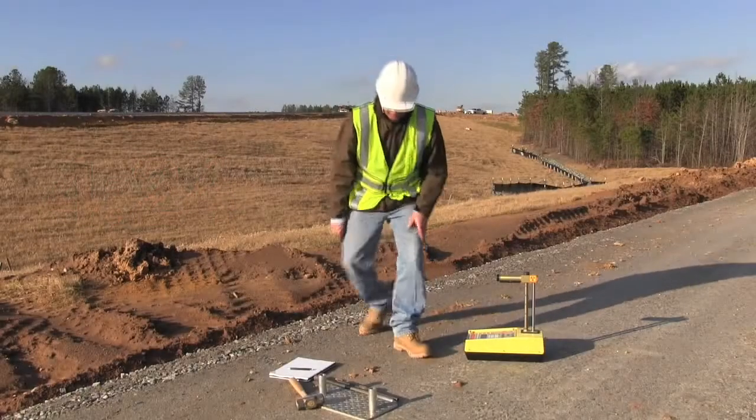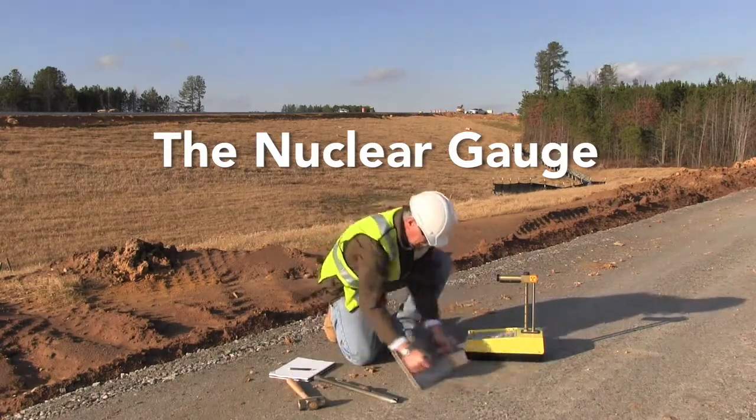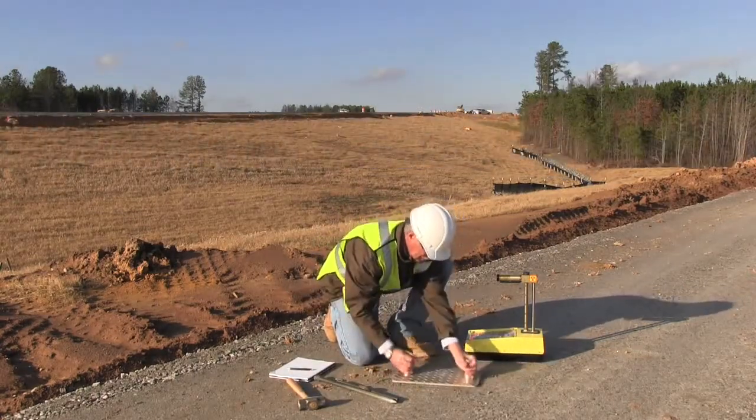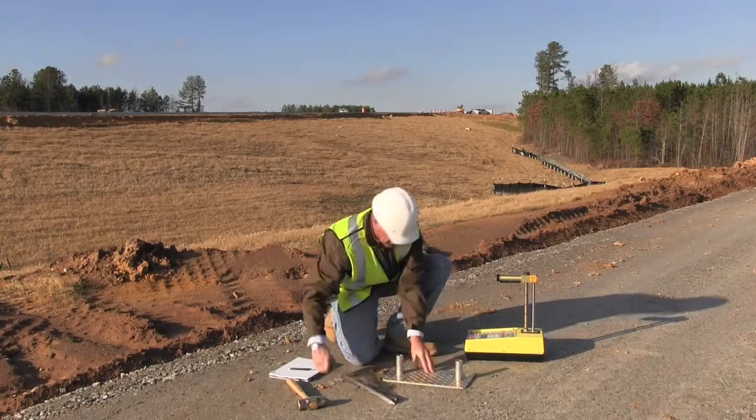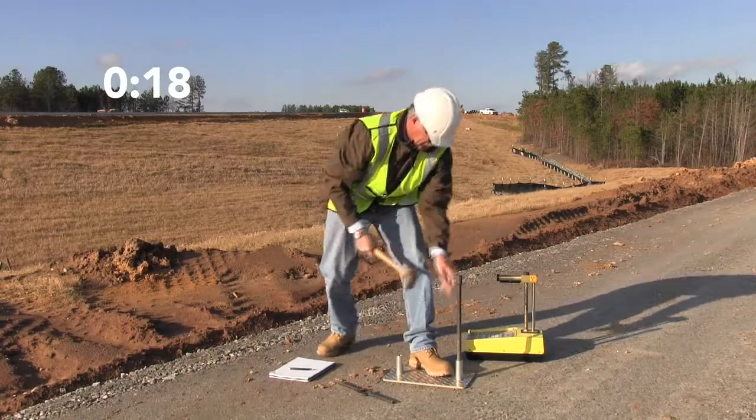With the nuclear gauge, a technician can perform a test fairly quickly and can get immediate values of density and moisture. Compaction values can also be generated if Proctor test data has been entered into the gauge.